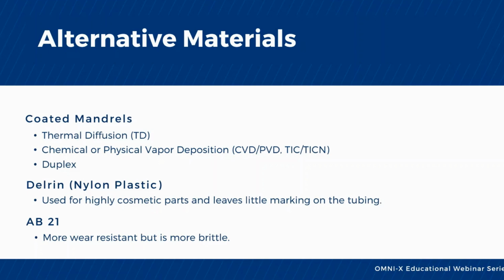Duplex coating often combines 2 different processes, normally nitriding and some kind of applied coating on the outside to achieve a hard substrate and lubricity combination not found in a single process. All of these coatings would require a lubrication engineered to support higher volume.